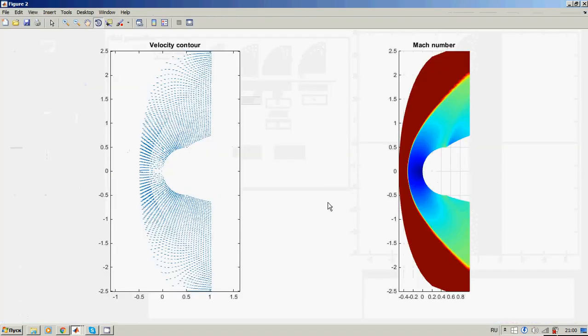So here you can see my Mach number curve, and you can see it looks pretty nice. You see deceleration of the speed at the leading edge, slight deceleration at the extra shockwave region. Same thing on the bottom, but less because your curvature is not that big, the angle change.